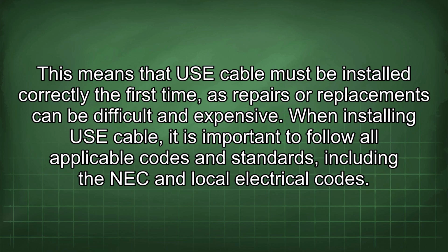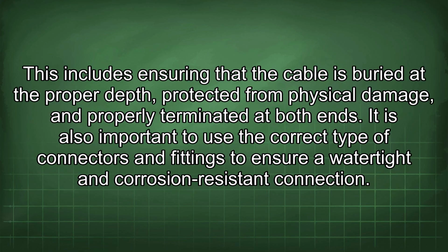This means that USE cable must be installed correctly the first time, as repairs or replacements can be difficult and expensive. When installing USE cable, it is important to follow all applicable codes and standards, including the NEC and local electrical codes. This includes ensuring that the cable is buried at the proper depth, protected from physical damage, and properly terminated at both ends.